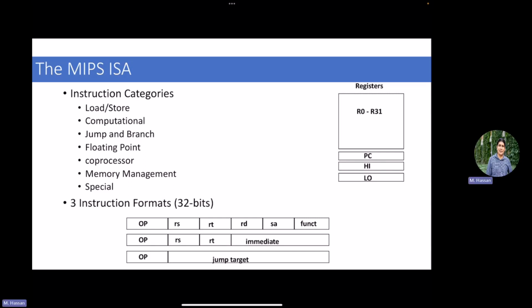Why is this a good idea? Well, because this simplification allows you to optimize your hardware significantly. It allows for better compiler-optimized code because now the instructions are simpler. So I don't need to do a lot of packing into one instruction. And because the hardware is simpler, I can put more of that hardware in the circuit. And also I consume, and that's the key point, much less power, right?